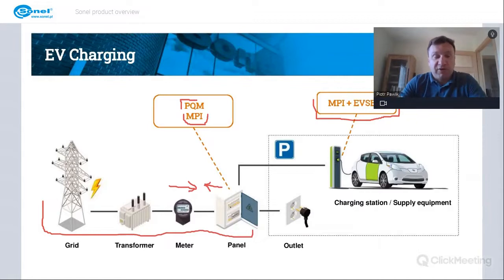If we go with our top model, MPI 540 PV, then we can check all of the components of electrical safety of the charging station. This new MPI 540 PV also has a possibility to program a certain sequence, so the meter will perform all the measurements in a sequence. We just connect the plug into a charging station, press the start button, and the meter will lead us through all different types of the tests. That is very convenient.